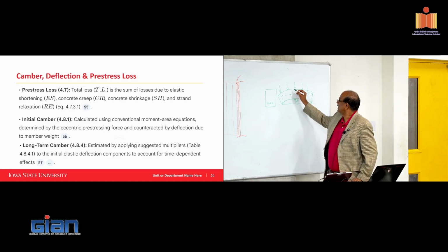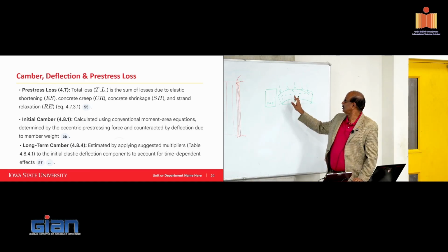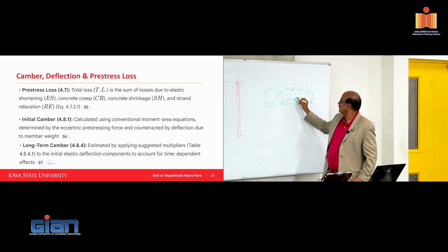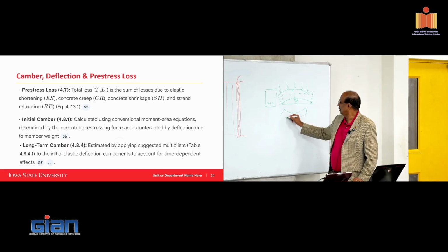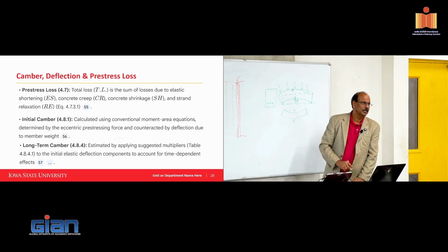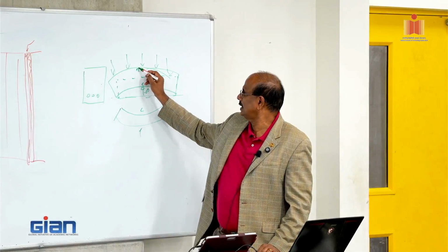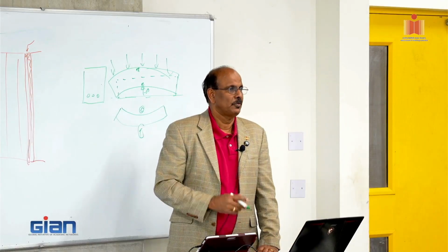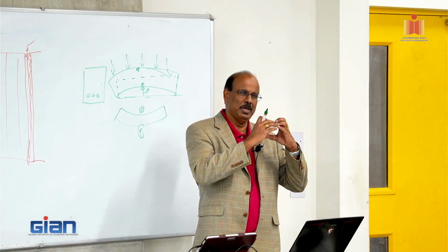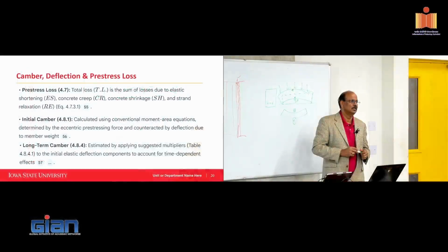So this is going to be, this is compression, right? Sorry, that's tension. This is compression, right? But when I load it, it happens the opposite. You're going to have compression here and tension there, right? So basically, if I'm coming from here to here, I'm counterbalancing that tension with this compression. So if the beam is staying flat, the beam only has axial compression. It doesn't have anything else. You see that?